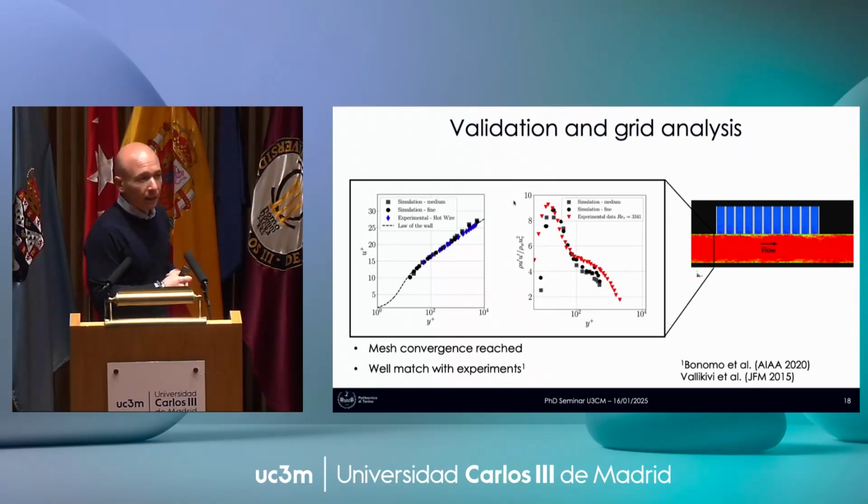So here I'm replicating the flow conditions in Brazil, because there we have easier access and we can perform the measurements when we like. And what we found is that the results are more or less grid independent for the second grid, the one of 40 voxels per millimeter, the one that I call medium.